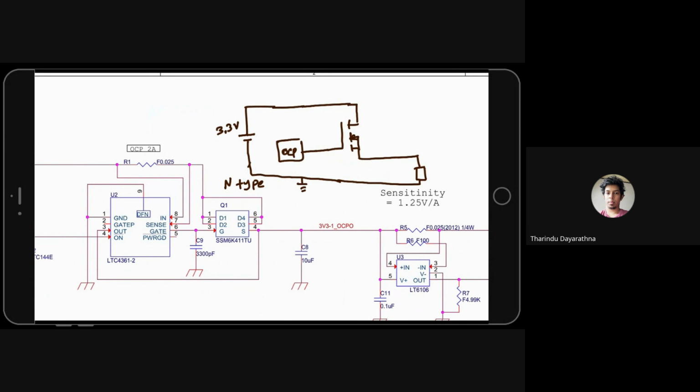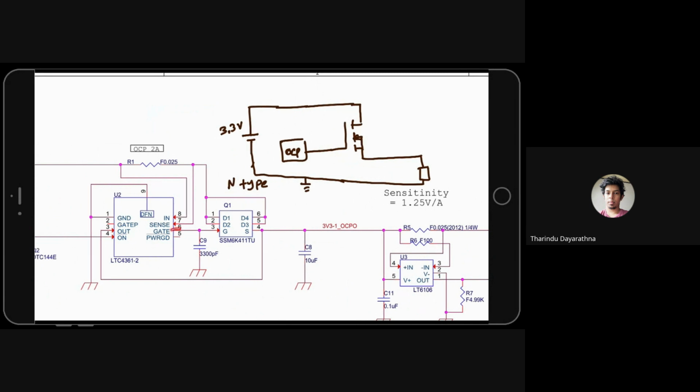You can see here there's a gate driver that comes here with the capacitor to generate a little bit higher voltage. As I remember, it's about 6 volt output, okay? So if the OCP outputs 6 volt, this circuit will run without any issue. If the OCP outputs 0 volt, this will be cut, no power going to the load, okay? That's how we control the power, okay? Understand?